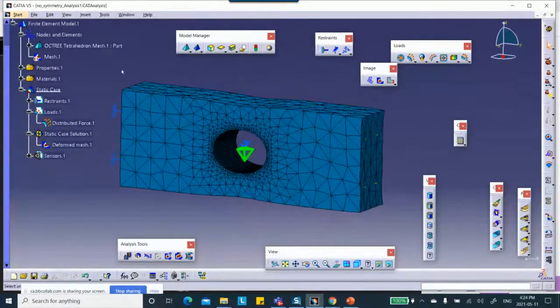And you're absolutely right. But stay away from that end, because at that end, you're not applying 2,000 pounds the way you intended it. This emulates that process. But in here, the stresses are quite good. This is called the Saint Venant principle. In other words, if you stay away from the source of disturbance, things are going to look the same. Well, you get the picture.